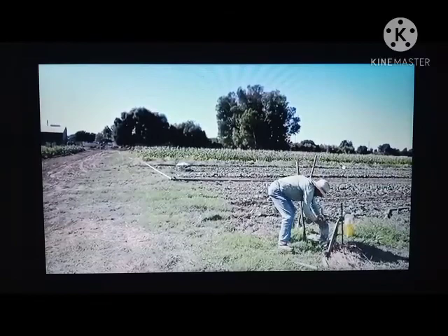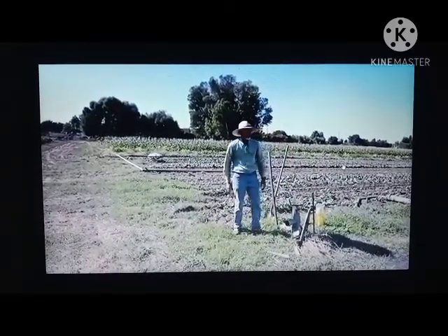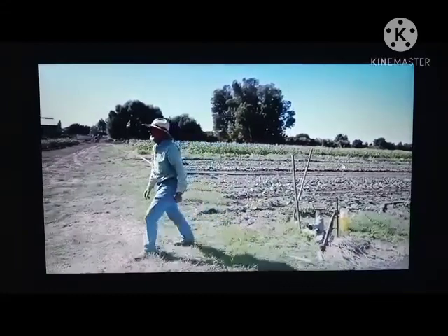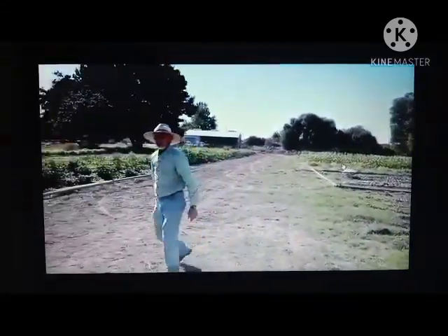Each one of those gates can put out, depending on how open they are, as much as 16 gallons a minute. We usually have a gate every 60 inches, so we're going to put out 64 gallons a minute onto our field to do basically 3 beds. This farm has been leveled to grade. A laser level machine comes out and makes your field have maybe a 1% grade, so the water flows downhill. That's an important concept in furrow irrigation, but you don't want it to flow downhill very fast.